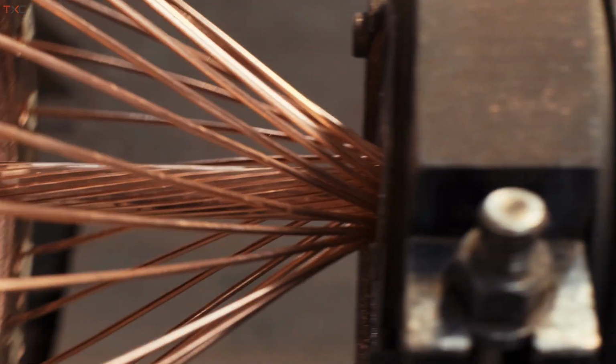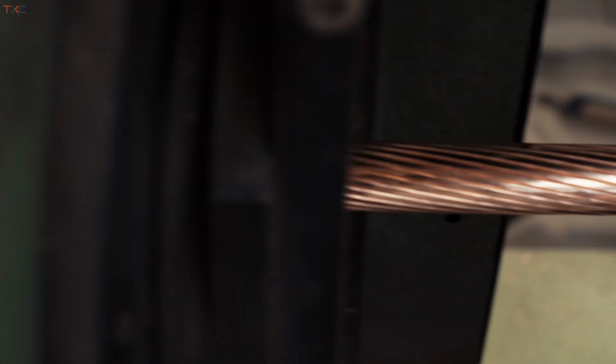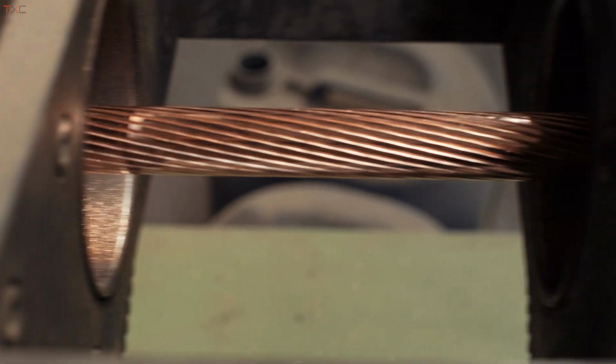So what we see is that once you double the speed from 400 to 800 gig and future 1.6 terabits, the copper cabling is becoming shorter and shorter, and thicker. On the flip side, what we're doing with AECs, it's called active, is we're placing what we call a retimer. It's a type of mixed signal SoC that's placed inside the cable to extend the cable link with the copper technology as your transmission speed goes up.